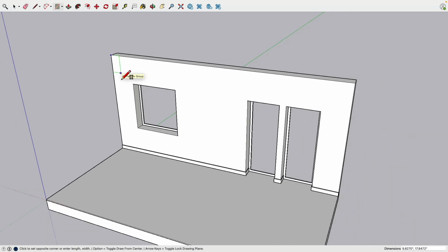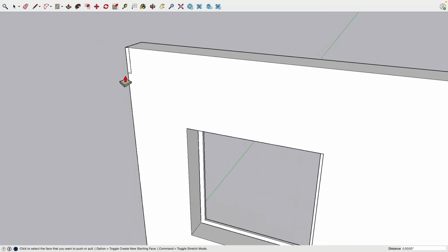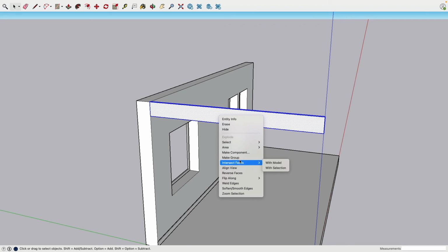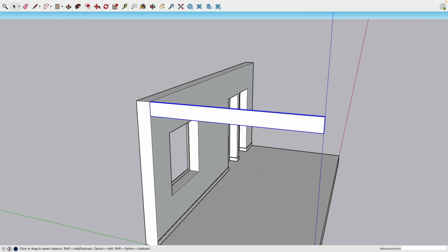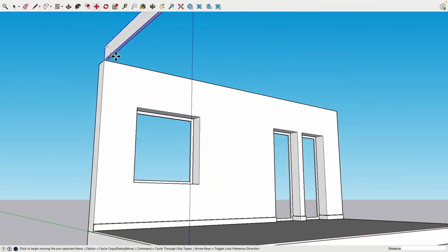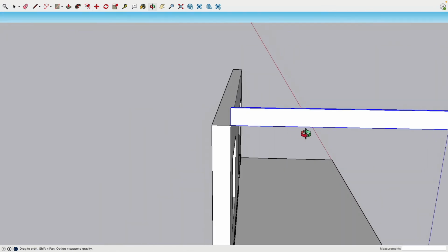So we draw here a rectangle. This will be 1.5, comma, 9.5. There we are. So this is kind of like a trimmed down joist. Then push and pull, triple click, group. This has to go upwards because this is right under, or inside, the ceiling. There would be drywall under it. We are removing the drywall.